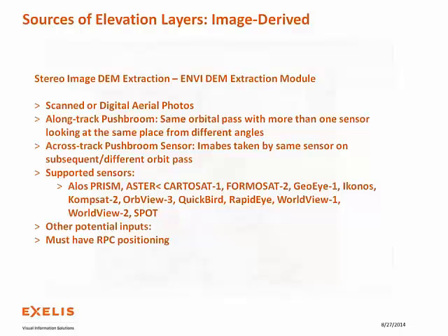The output surfaces, like I said, are DSM surfaces. Scenes with significant surface layers like buildings, trees, or other things do not lend well for the DEM extraction if they're mixed. So some people, for example, if they have a big city on a very steep hill right next to an ocean or something that's really flat, there are ways to mask things out and process things differently to still get a good result. It's just something to be aware of.